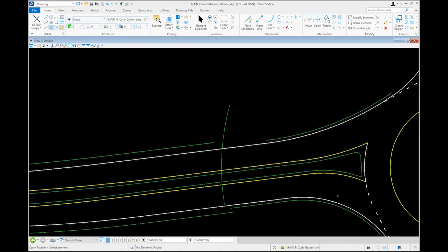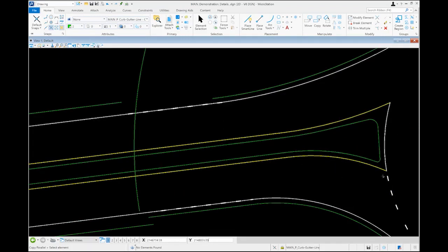For our crosswalk, we typically want to have that set back at least one car length from the edge of the circulatory roadway. Commonly, we try to get it exactly one car length, but there is some flexibility if you have things like an outside apron and need to push it back one extra car length. So the dimensions we're going to use are in the range of 20 to 25 feet to establish that car length. And we're going to use a 20-foot offset for the purposes of this demonstration. I'm going to measure that from the edge of this raised splitter island, which gives us just a little bit of buffer to that painted lane line.